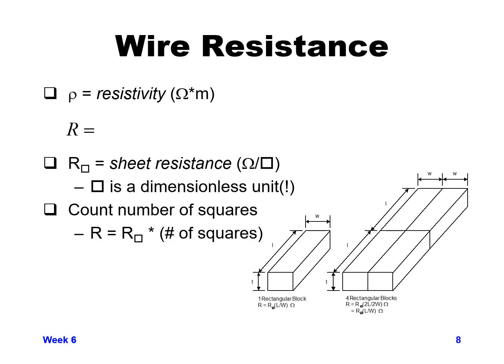So first let's go through how we calculate wire resistance. And the first thing to note is depending on the metal you have a certain resistivity to a particular metal that is formed as your metal layer on your IC circuit. And that resistivity is in ohm-meters.